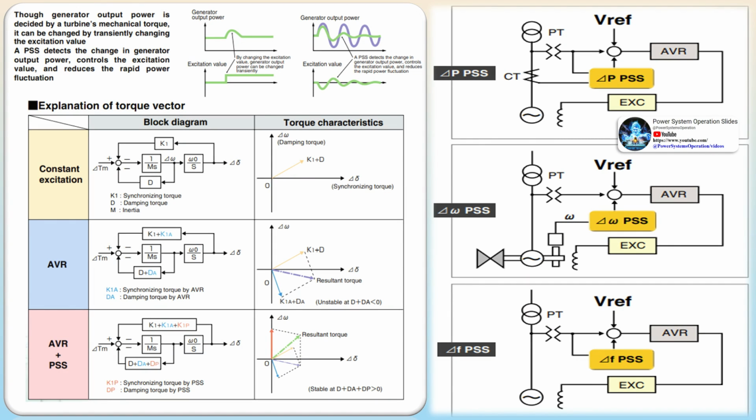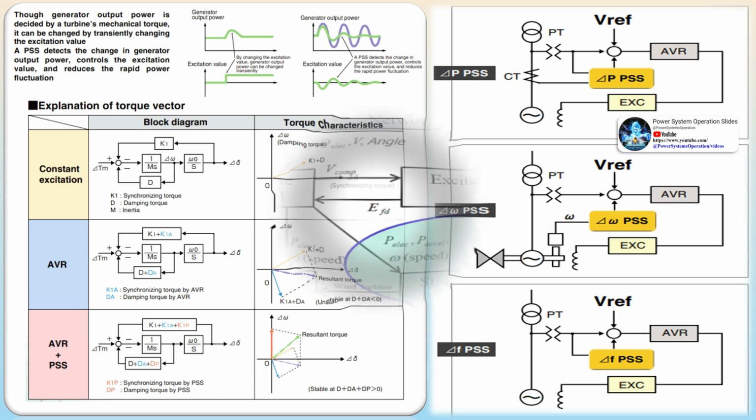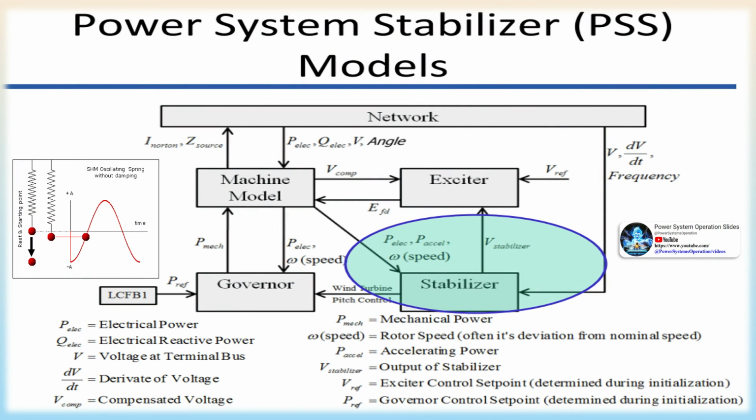Devices such as the Generator Automatic Voltage Regulator (AVR) and Power System Stabilizer (PSS) are widely used to manage these system instabilities. These control devices can be attached to power generation systems to help improve stability. The PSS works together with the AVR to maintain transient stability within a power system. The generator's output is primarily controlled by the AVR, but this system alone is not fast enough to respond to sudden glitches or faults. A PSS is added to the feedback to dampen rotor angle swings within a broad range of frequencies.